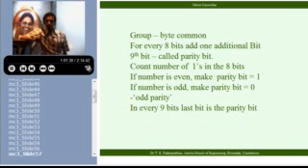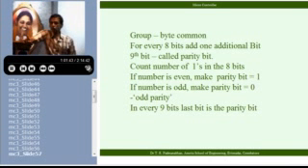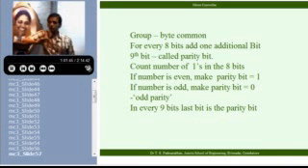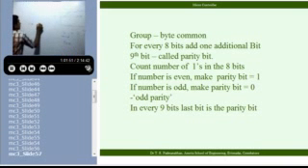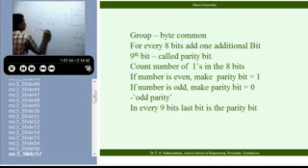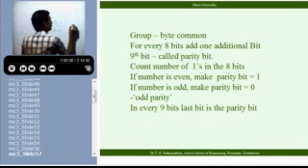So in a digital system, a binary system, this is just one general case; binary is a specific case. When I send a 0 or 1 as a bit, in a circuit I send 1 as a 5-volt signal and 0 as a 0-volt signal. Yesterday, in fact, Guru was especially asking this. A 0 is sent as a 0-volt signal, a 1 as a 5-volt signal. One case I have shown. Any value I receive more than 2.5, this I call a threshold.